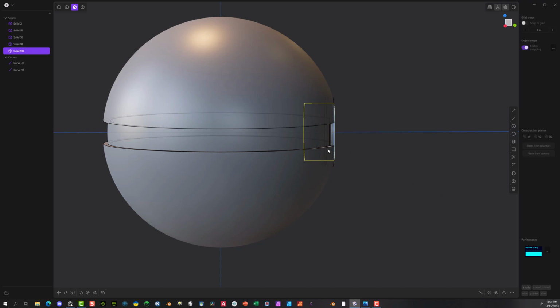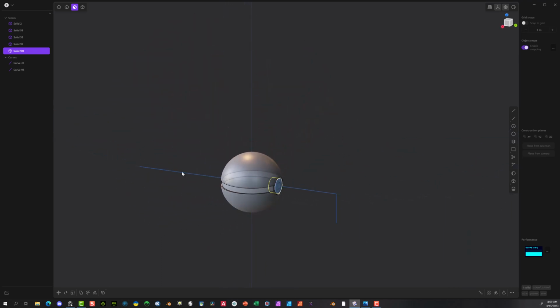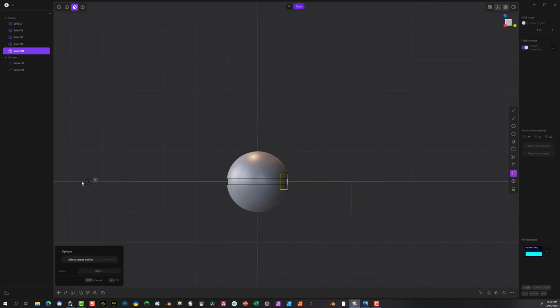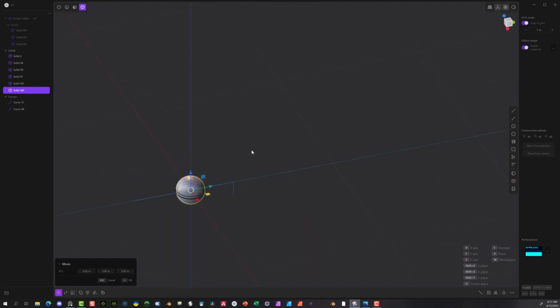Now, I'm also going to manipulate this, of course, but what I've done is I'm going to create another sphere to cut that. So I could do that now. Let's go ahead and go to the x-axis. Go ahead and sphere. And we're going to also put back the grid snaps. I'm going to create the 1 meter, but this time again, we're going to go to 0.94. Say OK. So we're going to hit the G key. And it's going to move each 1 meter. And it'll center off of this. Make sure it's all the way centered.